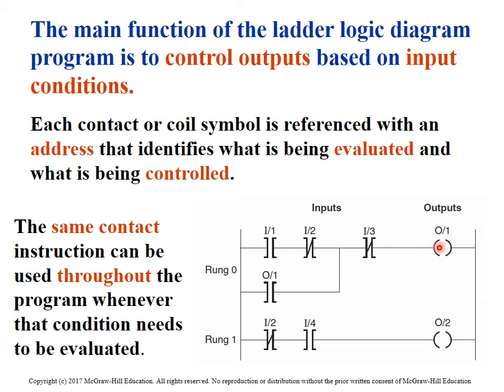One of the circuits that I want to make you aware of, that we will be experiencing a lot, is called the seal-in circuit. This is our first exposure to one. What you'll see is this contact here has the same address as this. They call it a seal-in or a start-stop circuit. It's a very, very common circuit in the PLC world. So what you have to do is make these two contacts. This has got to come on. This has to actually be off to close that normally closed contact. And this output will turn on,